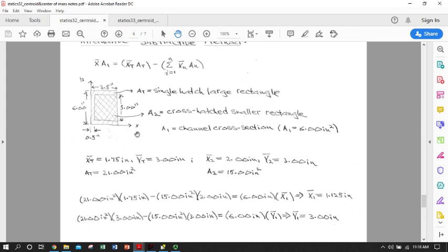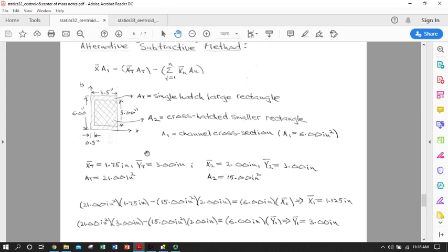If you see a centroid or center of mass for a uniform density problem on an exam or a homework, and you can use the method of composite parts, it's probably your fastest and most reliable way of finding it. If you're uncertain that it's going to work, you can always drop back and integrate. Use the fundamental definition of centroid to get it.